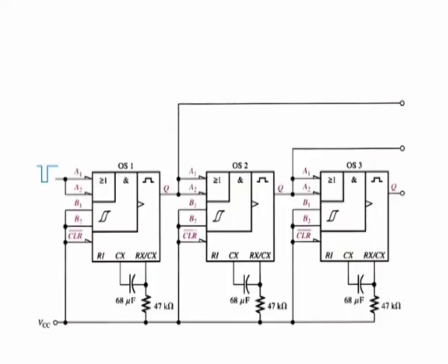An application. One practical one-shot application is a sequential timer that can be used to illuminate a series of lights. This type of circuit can be used, for example, in a lane change directional indicator for highway construction projects or in sequential turn signals on automobiles. The figure shows three 74LS122 one-shots connected as a sequential timer. This particular circuit produces a sequence of three 1s pulses.